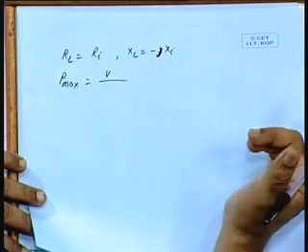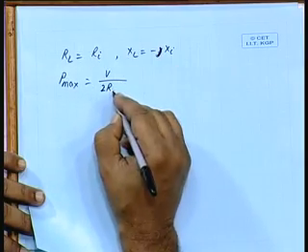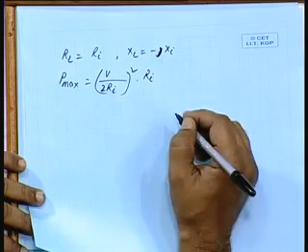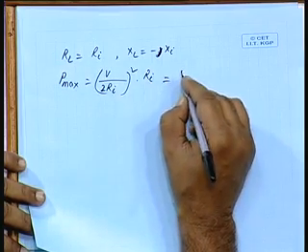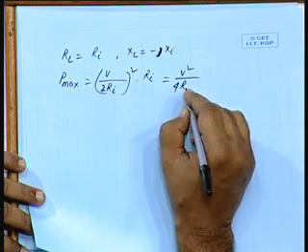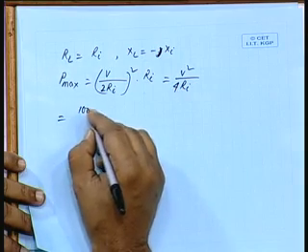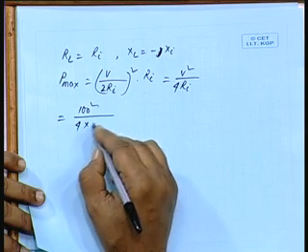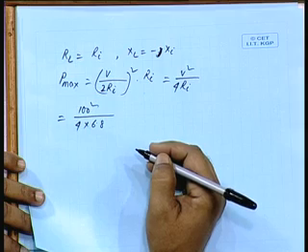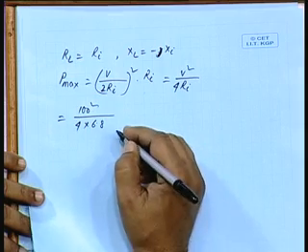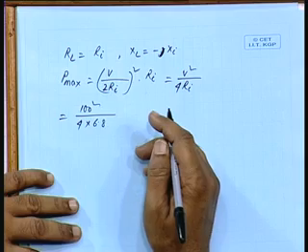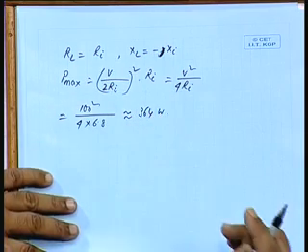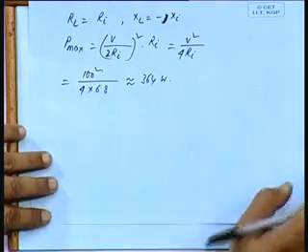It is RI plus RL, which is twice RI, into RI, RI is equal to RL. So, that will be V squared by 4 RI. So, that is 100 squared divided by 4 into 6.8. Is that all right? So, that will be the power approximately 364 watts. Okay. Let us take another example.